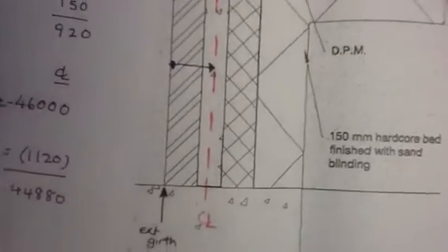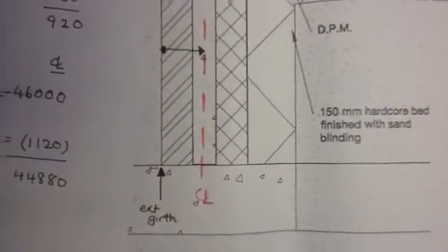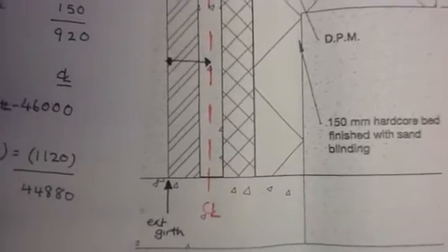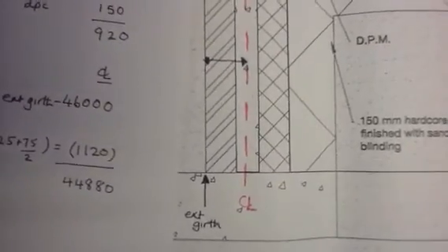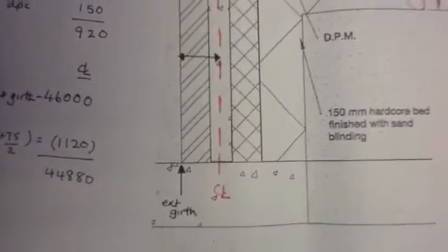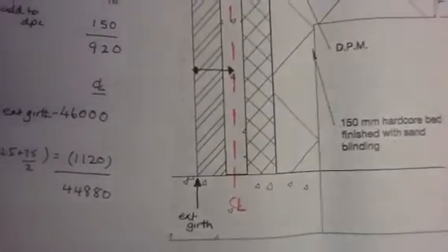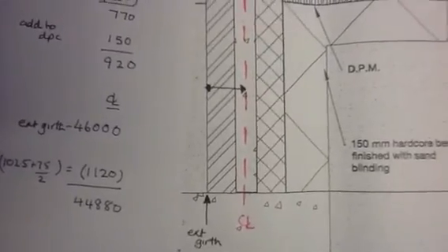The following video provides guidance on the measurement of forming of the cavity. The forming of the cavity is a metre squared item calculated by multiplying the centre line of the cavity by the height of the cavity. So let's first focus on the height of the cavity.